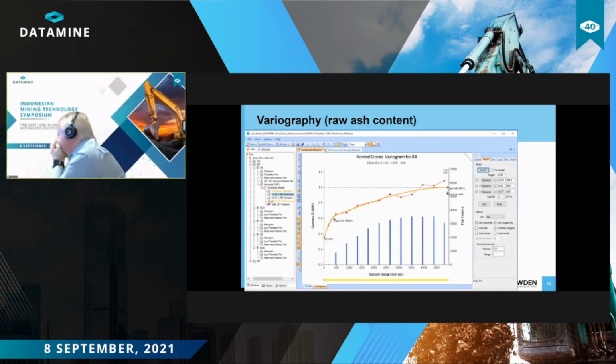We can move these points around just simply by clicking on them and dragging. This is a very useful and intuitive way of modeling variograms. So we can change the nugget effect, and we have a toggle for each of the spherical models it's employed, and we can simply drag and drop these to model as best we can the experimental variogram.